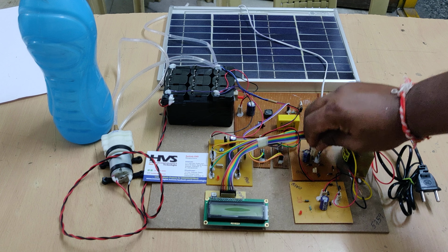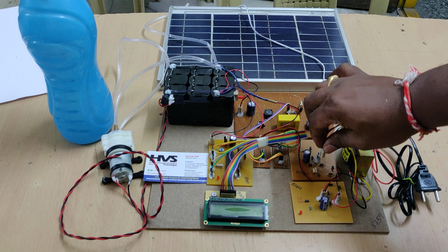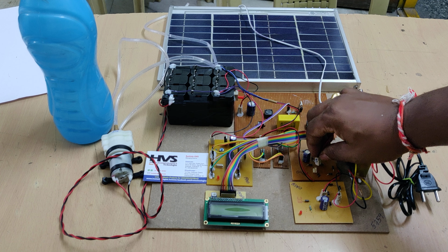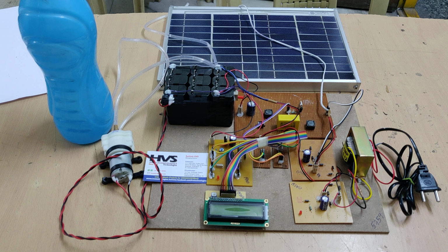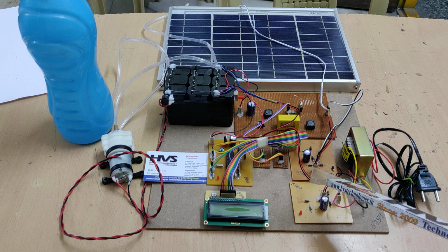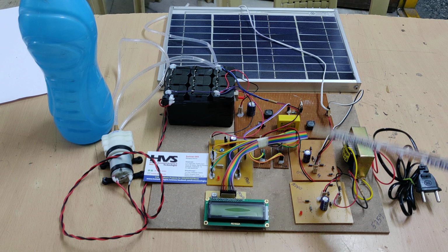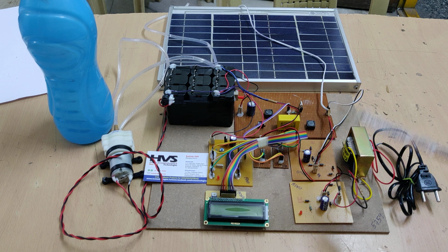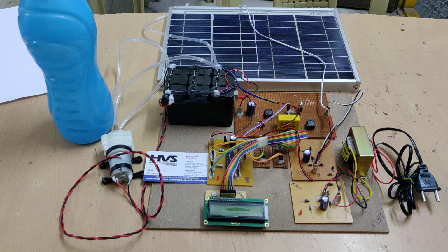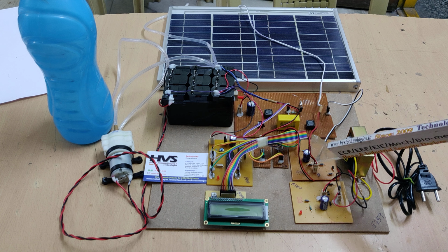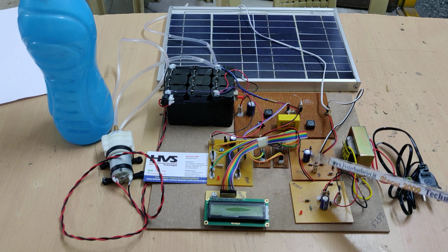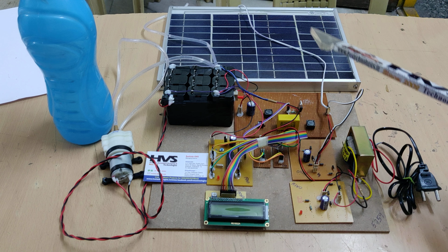Meaning if we connect this solar panel plus to plus, minus to minus, that is normal. Plus to minus, minus to plus is reverse polarity. In that case, if we place these 4 diodes, they will rectify the input to plus to plus, minus to minus instead of minus to plus, plus to minus. So that we can protect the battery from reverse polarity connections. The output of this charging circuit is the input to the SEPIC converter. Then the controller will start reading the input from the solar panel and check it.